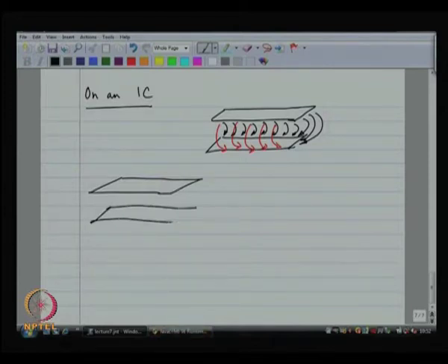Distance could be as large as 0.1 microns in your latest 28 nanometer process. In little older processes, it could be as big as 1 micron. Let us say you are talking about a 0.13 micron process. The gap between two metal layers could be as large as 1 micrometer.